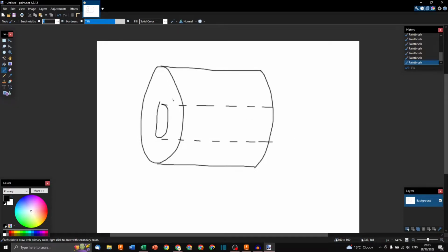So a sketch is a 2D object, drawing, that you want to create, and you will then extrude into a volume. So you should have in your head the object you want to create, and with this, so that's the wheel we're going to be making, you want to select a face that will be easy to sketch out and that you will easily be able to extrude.